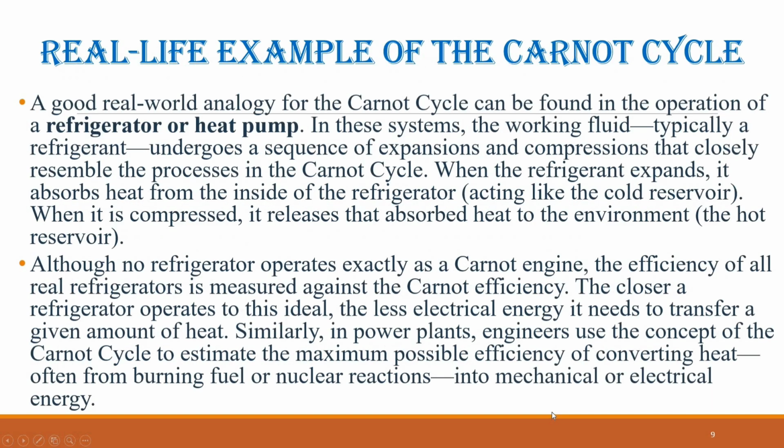Real-life example of the Carnot cycle. A good real-world analogy for the Carnot cycle can be found in the operation of a refrigerator or heat pump. In these systems, the working fluid, typically a refrigerant, undergoes a sequence of expansions and compressions that closely resemble the processes in the Carnot cycle. When the refrigerant expands, it absorbs heat from the inside of the refrigerator, acting like the cold reservoir. When it is compressed, it releases that absorbed heat to the environment, the hot reservoir.